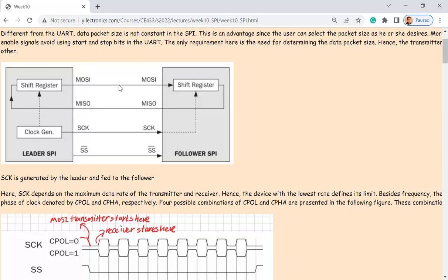No, I mean for the four modules, for the four logic modules, which one? So if I have to let you draw the diagram of the light sensor or the sensor here, right? What do you need? First, a light sensor. What is a light sensor? It can be a photodiode. Okay, it's a semiconductor material, right? It receives light and converts it into current or voltage. Usually current. It's a photo effect, right? Einstein won that Nobel Prize 80 years ago for that. Right? So photons can be converted into photocurrent. And photocurrent being converted into voltage.